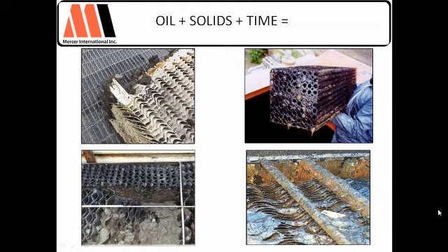I hope you got the idea that solids are the component that causes the issue in oil-water separation. Now, it's oil-water separation design, but it's not so much the oil that causes the problem with meeting compliance. It's the solids. And if we deal with solids, we're going to have success in our separation.